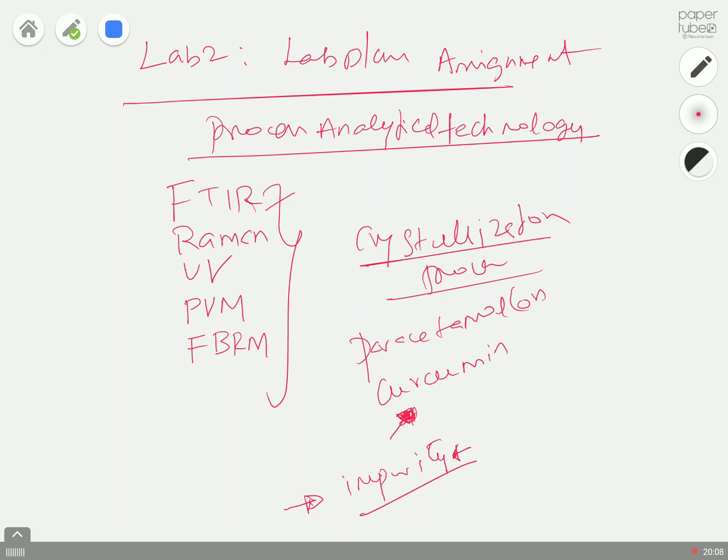do that. So we will perform some multivariate analysis, and then I will convert those spectra into concentration, and what I'm going to give you is that concentration versus time. So you are going to fit some kinetic expressions to that data, and then you are going to talk about the different PAT tools that we used in the experiment and their working principles, and then how it's converted with software which is used to convert your spectra into concentration, and how we converted it.